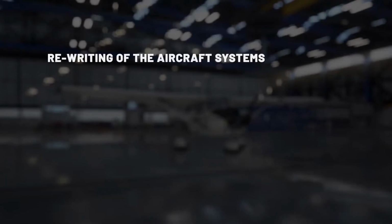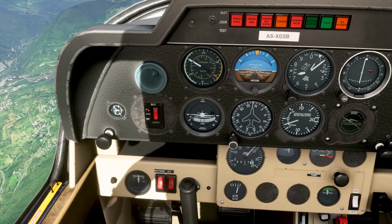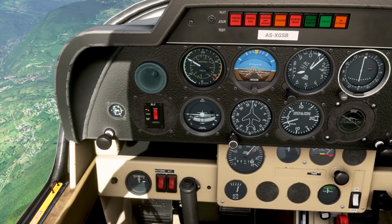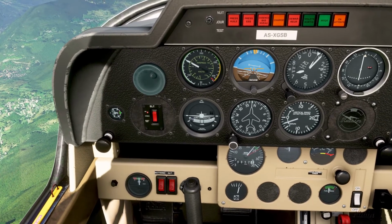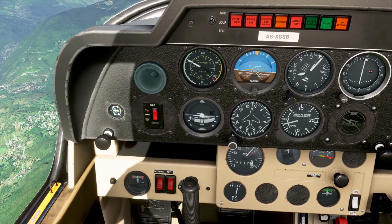So we also made improvements to systems in the simulation other than aerodynamics. We improved the load factor simulation, which also improved the way the ball, the turn coordinator, is simulated. It's now much more realistic, which means that when you fly asymmetric, if your aircraft skids a little, the ball is moving to the side exactly as it should. And you can now control your flight with the rudder and make it symmetric using the ball much more easily, because it reacts much more realistically than before.